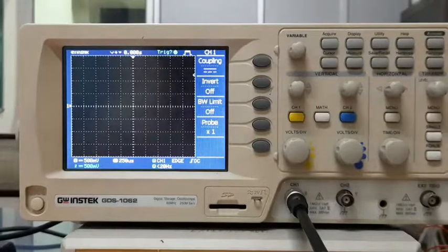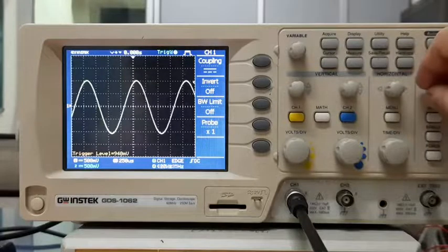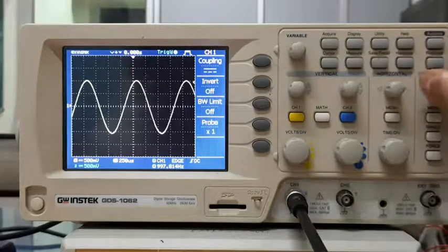So this is about 1.2 volts. If the signal never crosses 1.2 volts, you will not see anything because the oscilloscope is just not refreshing. It's not showing you whatever is being fed to it, right? Will my signal cross 1.2 volts? No, because I have given it a 1 volt peak amplitude signal. So it will never cross 1.2 volts, and that's why I am not seeing it. So if the amplitude of my signal is 1 volt, that means my trigger should be less than 1 volt, right? So I'll set the trigger level at less than 1 volt, and as soon as it is, I'll start seeing the signal.